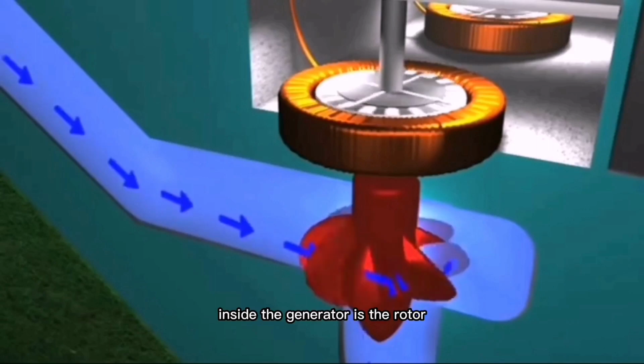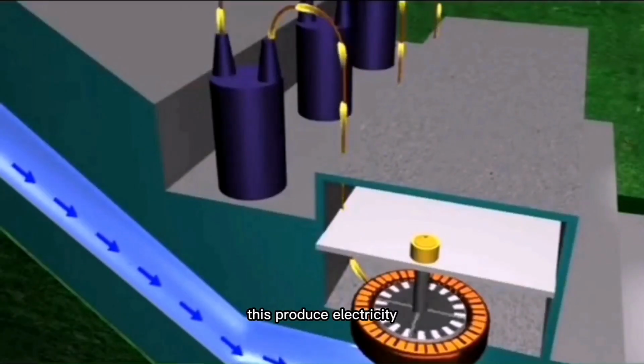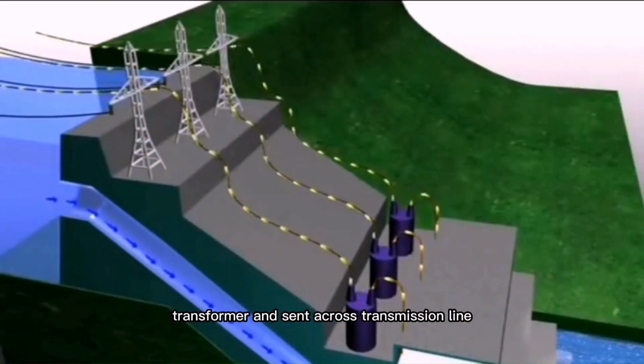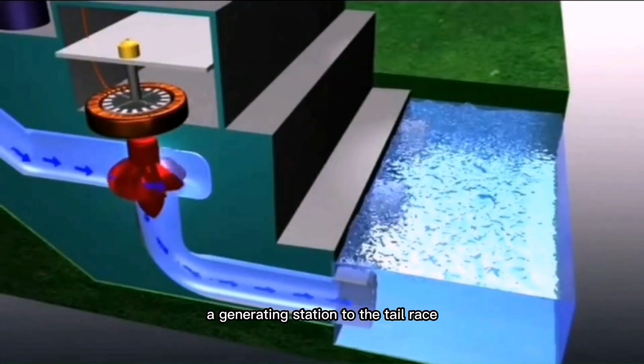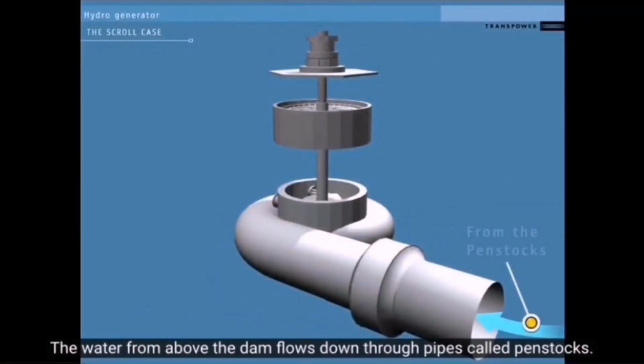Inside the generator is the rotor that is spun by the turbine. This produces electricity that can be stepped up in voltage through the station transformer and sent across transmission lines. The falling water, having served its purpose, exits the generating station to the tailrace. The water that comes from above flows through the penstock.